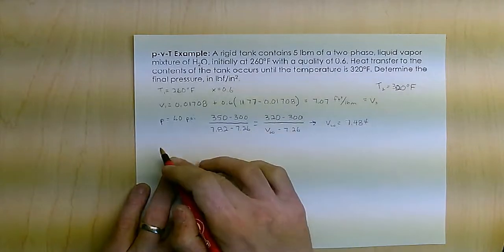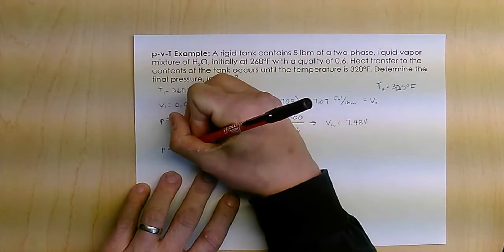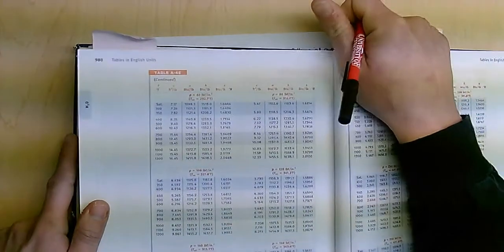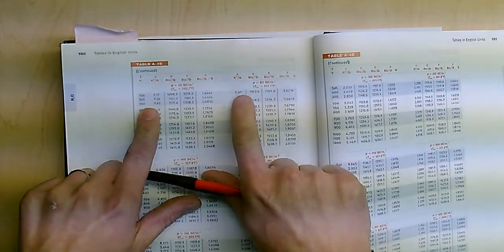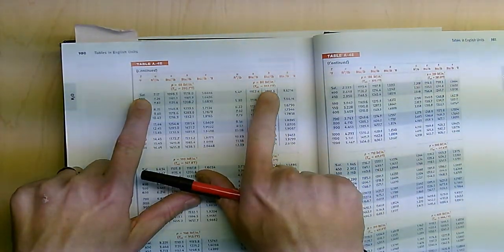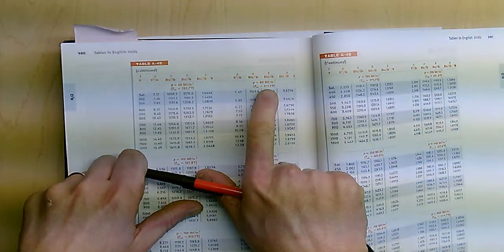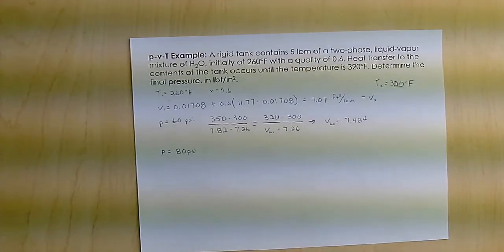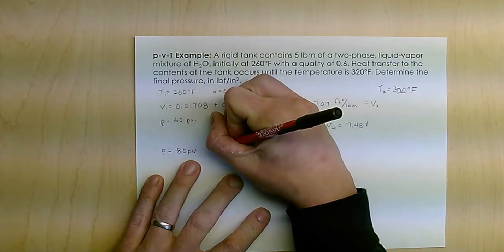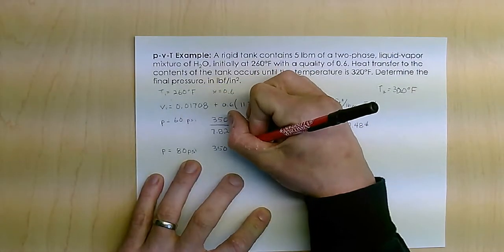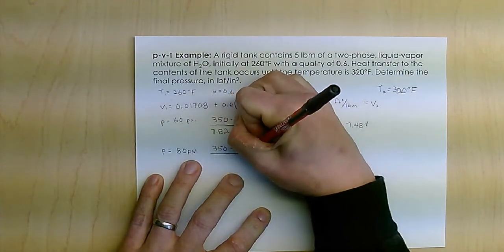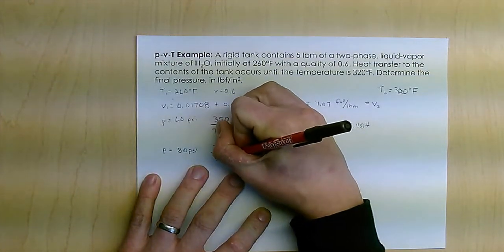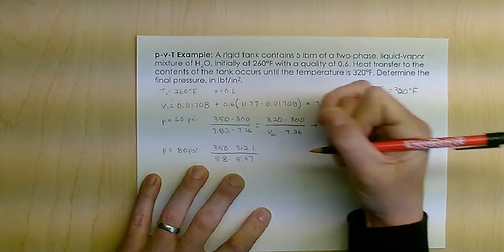Now I'll do the same thing at P equals 80 psi. Now this time, remember in this equation, I have the saturation instead of 300. So the lower temperature is actually 312.1 and 350, and then my volumes are 5.47 and 5.8. So I still have 350, but instead of the 300, it's 312.1. And the volumes associated with those are 5.8 and 5.47.